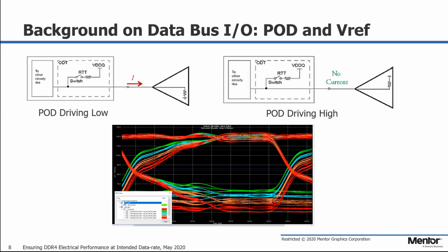Next, I would like to cover some background info on I/O technology for data bus. One of the major market forces acting on the DRAM industry is the demand for lower power consumption of the memory devices. To this end, DDR4 uses the new drive standard known as pseudo-open drain or POD.